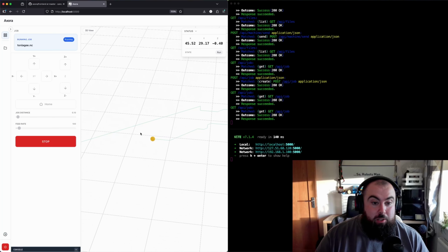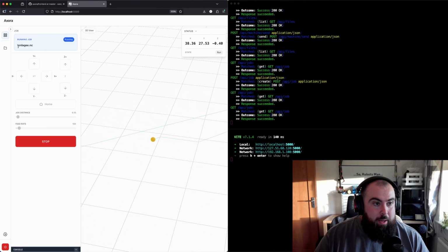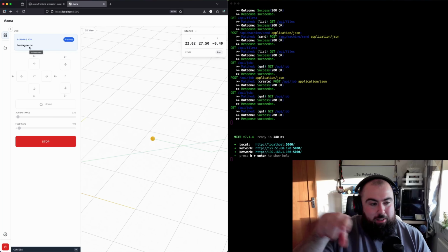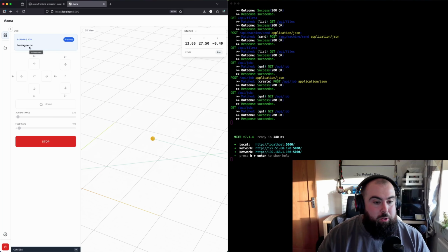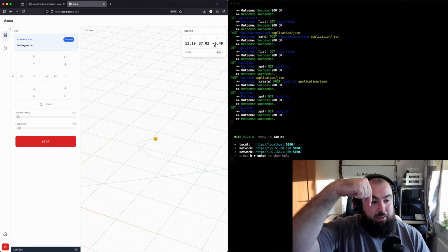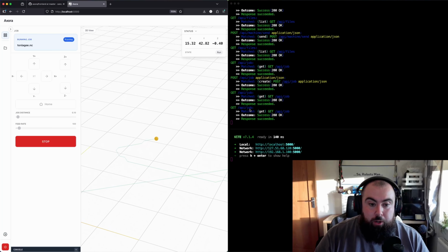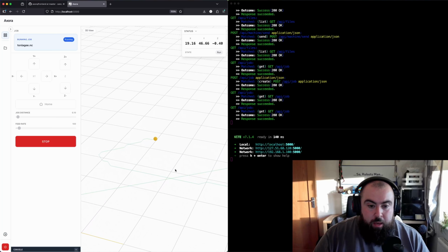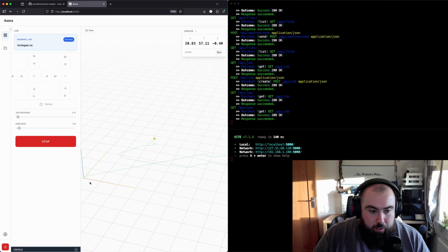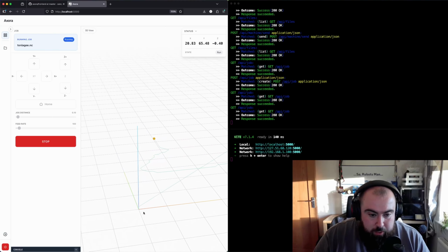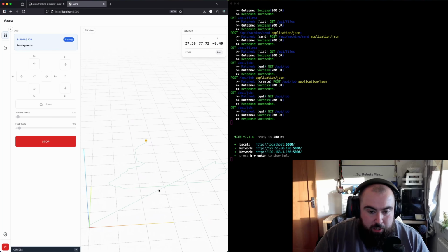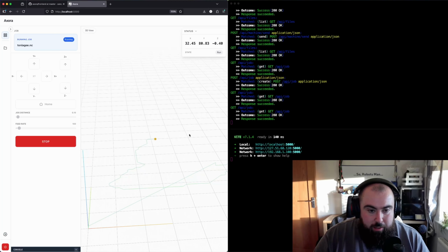And this is an actual toolpath that I had. Tonlagee is the name of a mountain in Ireland, and this is kind of an abstract contour map of that mountain that I was engraving before. Because this is actually an engraving path, the Z is minus, so this would indicate that the bit is down in the work, currently carving out its engraving. So I can zoom out on this so you can see the picture a bit better, and you'll see here, if I turn it around, you can see where the bit lifted up to its safe height, cleared, traveled all the way over here, and then dropped back down to its working depth, and then it's going to keep doing that.